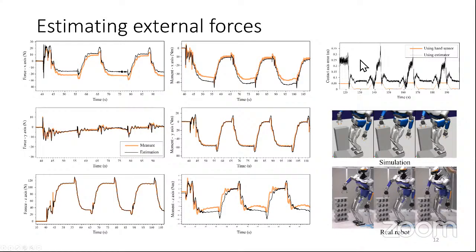And here we show that I can even rebuild the axis that is the closest to the contact, given these measurements. This axis has 7 centimeters of error between the contact point and this estimation. So we can also get information on the application point using this estimator.